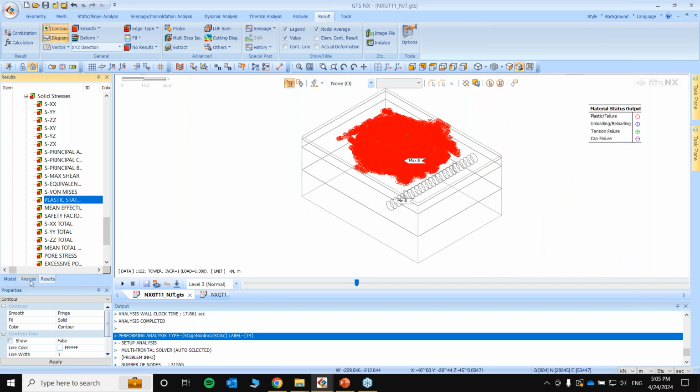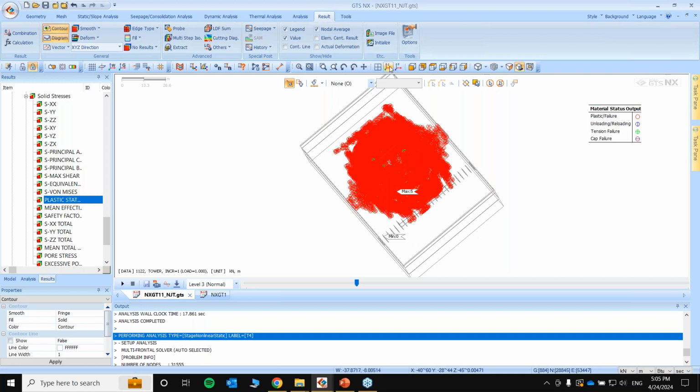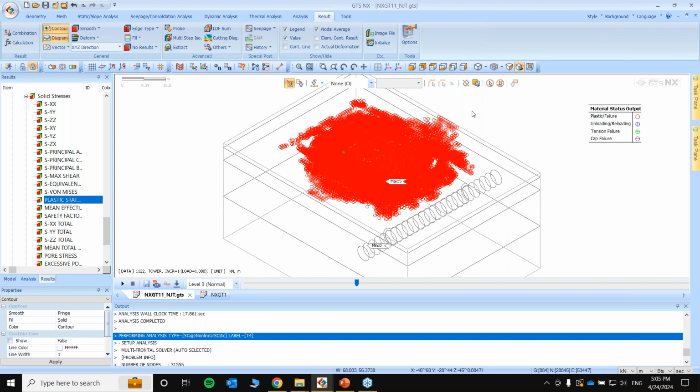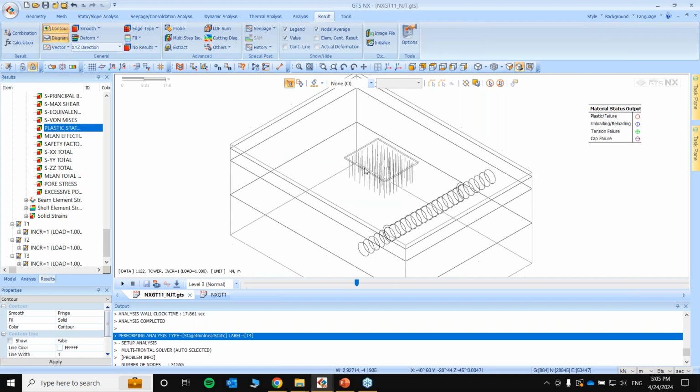Due to the presence of the building and all the load applied, you can see a large amount of plasticity accumulated quite close to the vicinity of the building. Now, our goal should be that in the long run, this plasticity will be slowly taken up by the surrounding soil and the stresses will be dissipated. If not, then we are looking at either soil failure or a building collapse due to foundation-based failure or maybe punching failure. So this is something that has to be kept in mind.